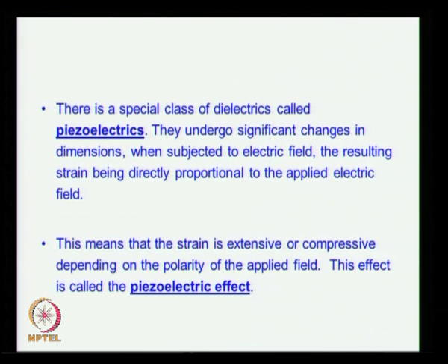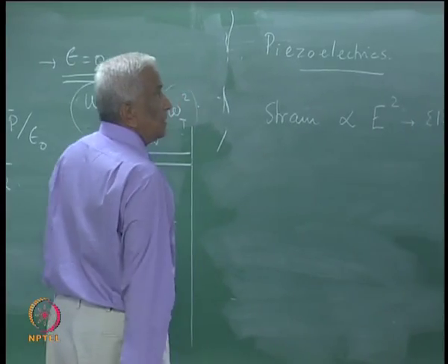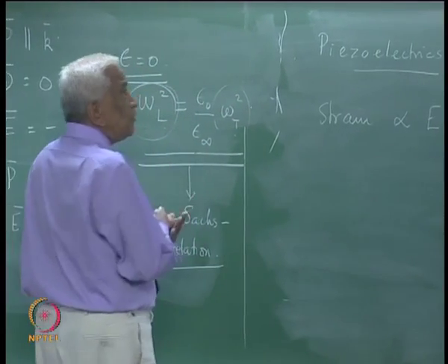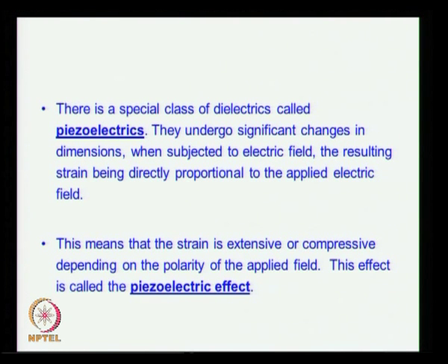But piezoelectrics is different. This is one special class of dielectrics where there is a significant change in dimension when subjected to an electric field, but in a piezoelectric the strain is proportional to the amplitude of the field.